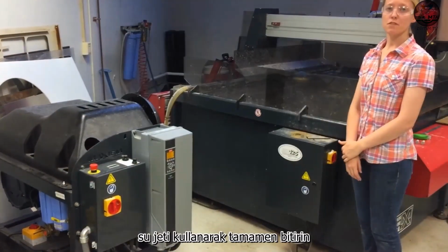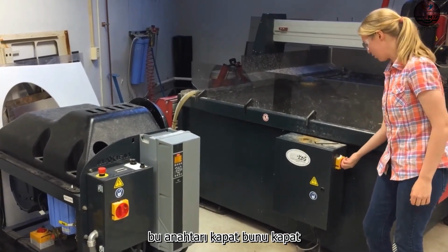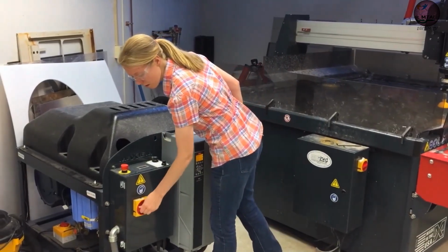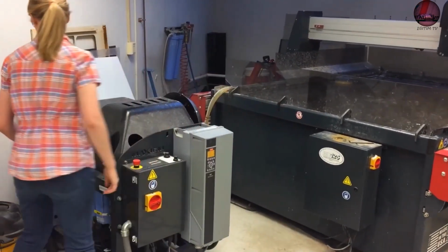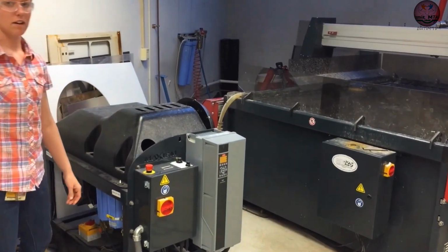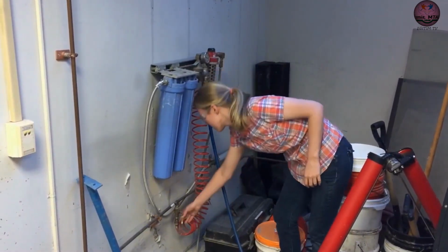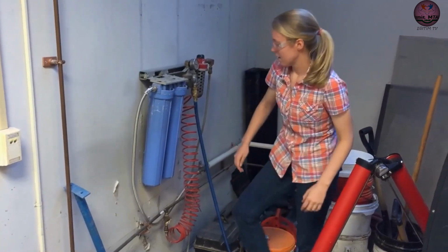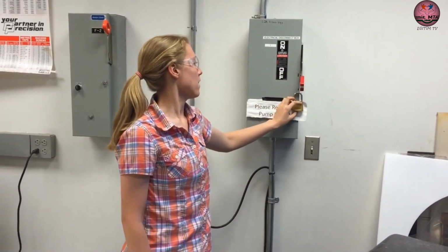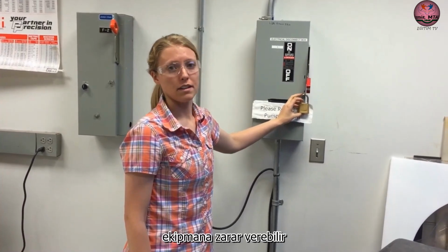When you're completely finished using the water jet, do the opposite of what you did to start it. So turn off this switch, turn off this switch, go back here, and turn the motor to off. It'll quiet down. Next, turn off the water and the air. And finally, turn the breaker off and lock it back. And remember, this order is important because if it's not done in the correct order, it can damage you.